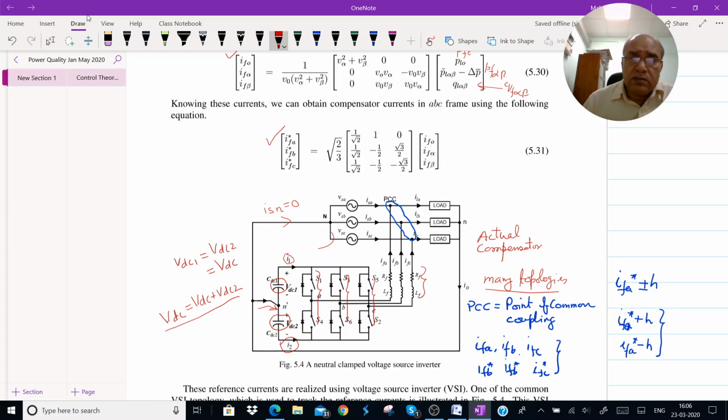This part does not play an active role because the load impedances are quite high as compared to the source impedance. Hence the current will nearly follow the source side path, this path. And ILA depends upon this voltage. So while modeling, we consider the source part rather than the load part. This is very important to understand because the equations which govern the voltage and current laws, Kirchhoff voltage law and Kirchhoff current law, will be applied to this path due to the least impedance path for the currents. Now, knowing this, we'll go further.